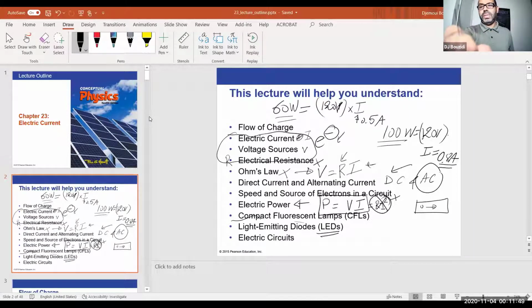Okay, you see the legs in here? They are at 2 different lengths. All diodes have that. And that is because they can only be connected in one way. The current can only flow in one way. This is how they tell you which way the current can flow on this specific diode. That's the convention for it. They make one leg longer than the other, so that if you want it to light up, you have to connect it in that fashion. You cannot do it in any other way.